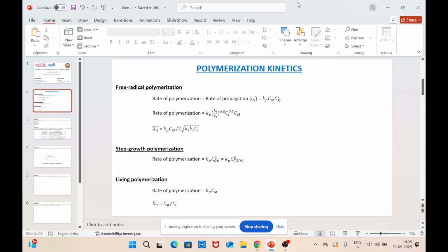In case of high temperature, the thermal energy that the polymer melt carries is going to be high. Because of this, they are going to flow more easily compared to one with a lower temperature. Because of the easy flow, the viscosity is going to be less, so the pressure that is going to be required is going to be low. However, at very high temperatures, there are also chances that there will be thermal degradation.